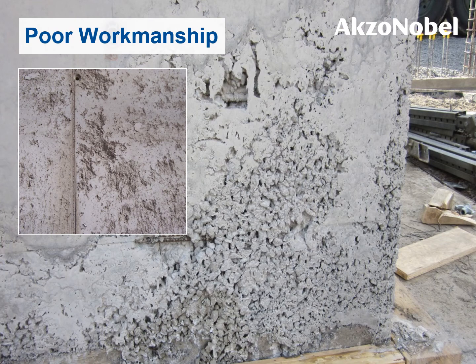And finally, poor workmanship, which is the root cause of very many concrete durability issues. In this example, we can see how the concrete has been very poorly compacted, leading to large areas of void at the bottom of the shutter. This concrete is extremely weak and requires appropriate reinstatement.